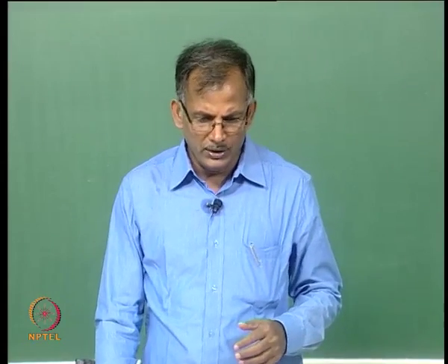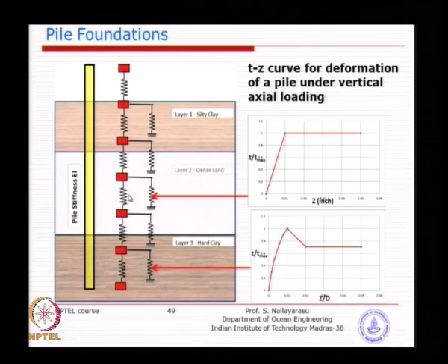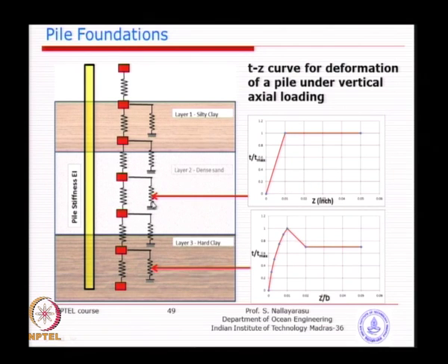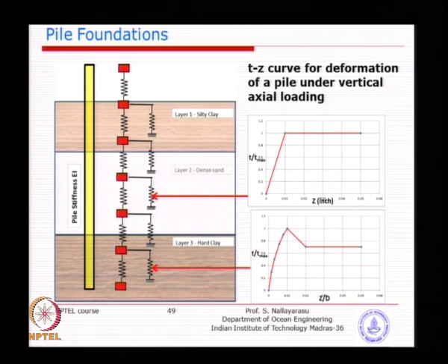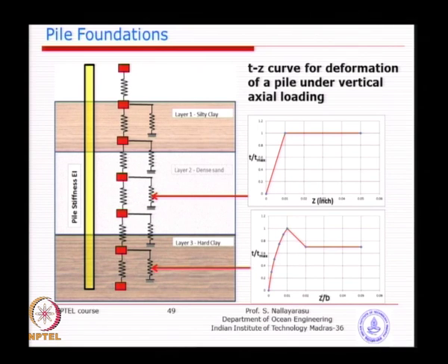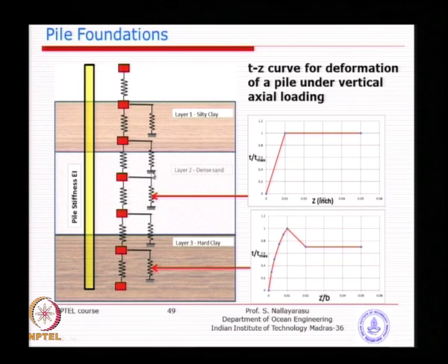So, what you are looking at, each of these pile segments is connected by a soil spring on the sides. Of course, this spring is representing the pile itself; for axial, you can find out EA, the modulus times your axial area. So, the side springs are attached to a rigid datum on a little bit far away ground.